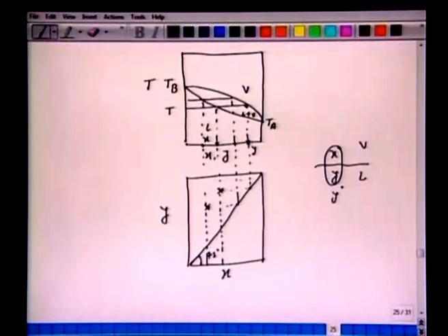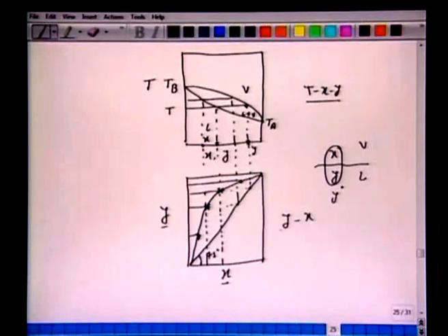Similarly, we can plot different x and y to obtain this xy diagram. So this is also an equilibrium curve, y versus x. The more important thing to note here is that for every coordinate y and x, the temperature is different. It's very important that you understand this. Although we don't specify temperature here, the temperature is different for every y and x. So the Txy diagram is one type of equilibrium curve, and a more simplified version is y versus x, which is also very widely used.